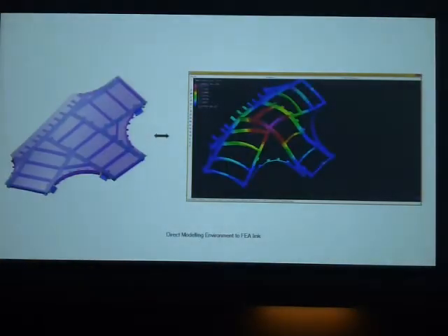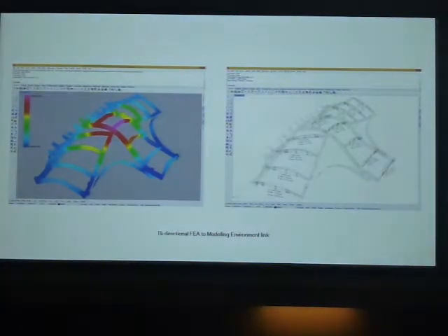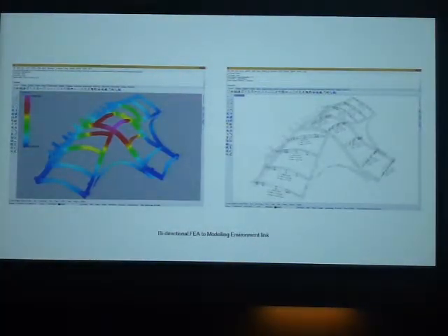So after all these models are generated, we need to make sure the models are correct before we send them off for fabrication. Our colleagues in New York have developed a live link between Grasshopper and our finite element analysis software, STRAND. This is a bidirectional link that can have the frames analyzed for structural validity and bring the results back into the Grasshopper environment. By using this connection, we were able to validate all complex conditions under all load cases.